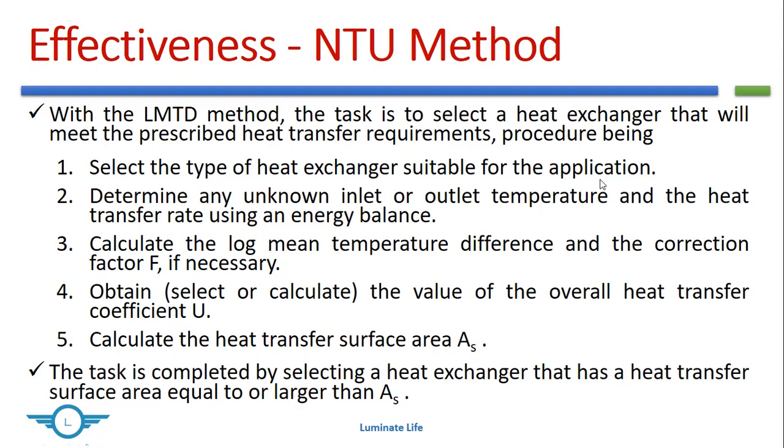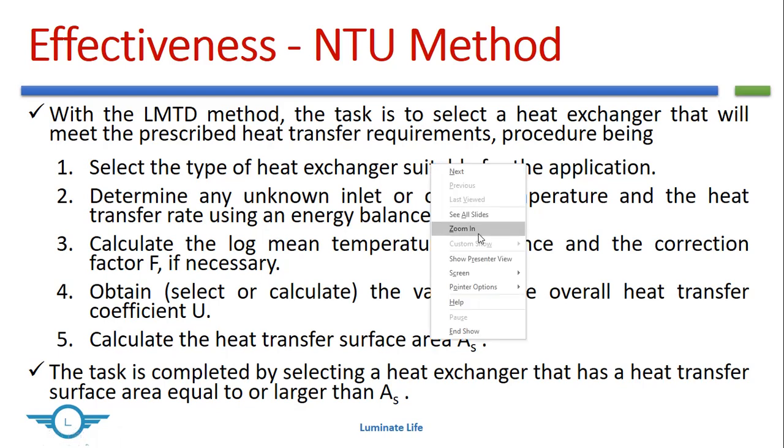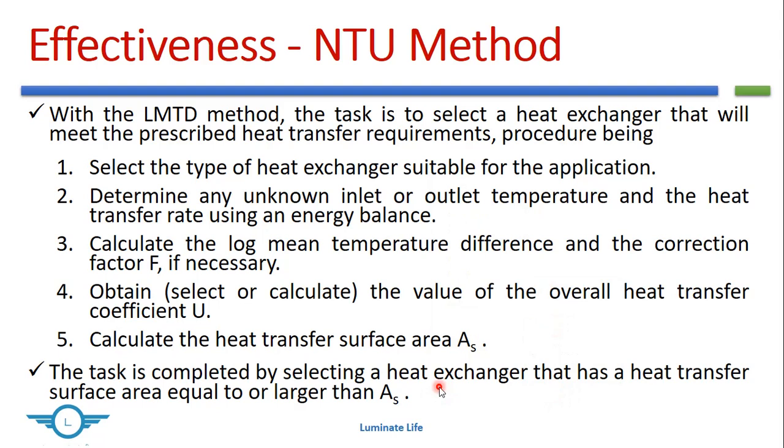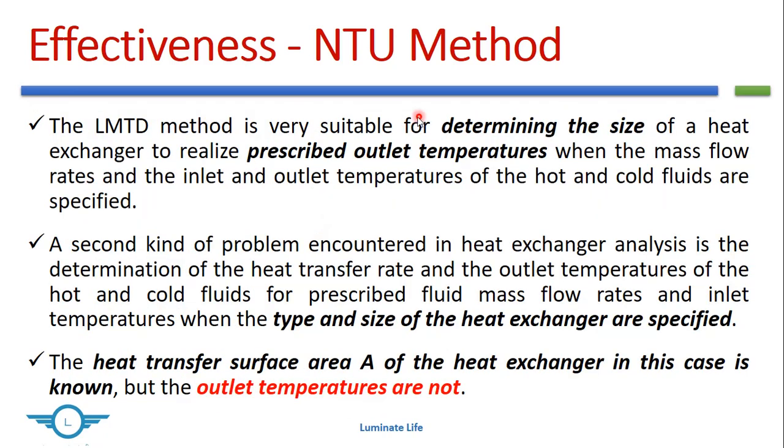From all this data, by equating the heat transfer rate with U A LMTD, we will calculate the heat transfer surface area A_s. Okay. Now the task is completed when we select the heat exchanger of the required area that we found. Now the LMTD method is best suited for determining the size of a heat exchanger which is required to realize a prescribed outlet temperature.